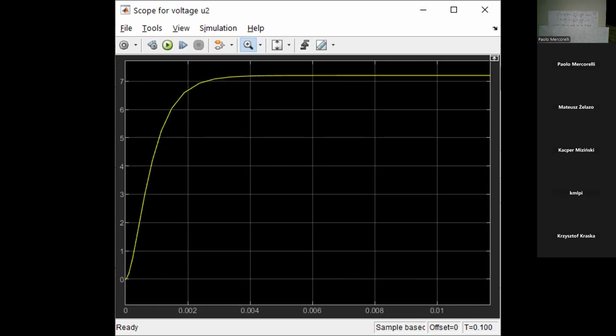Because of course, at the beginning, an exponential function can be approximated by a line. Now we can see the advantage: no oscillations. If the oscillations are not desired, it's 10 times faster than the original one, at least approximately, of course. I told you many times what the meaning of this approximation is. Because we have two time constants, not one, but in general, we can design very well.